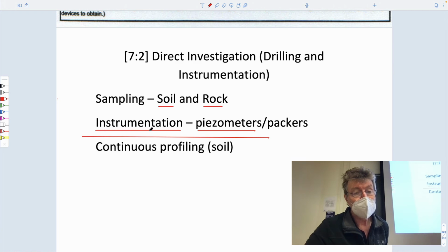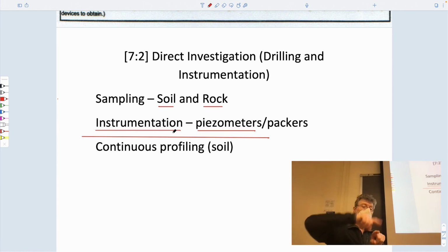If you leave an open borehole, you typically are required to seal it, so there's no cross-communication between portions within aquifers and across aquicludes. And so one useful way to seal it would be either to case it, so that the casing takes care of that sealing, or to put instrumentation in it, which only allows access to discrete zones.